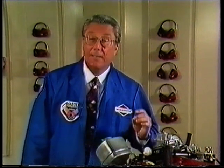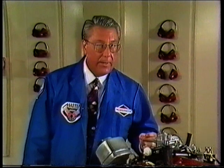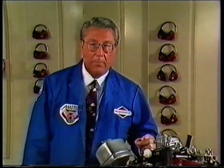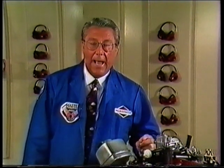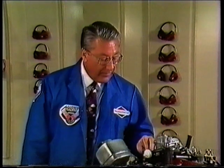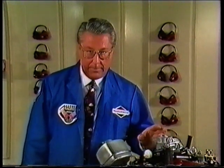In most of these hunting and surging problems, the cause is a lack of fuel, not an overly rich fuel condition. And believe it or not, more than 95% of all carburetor performance problems are caused by dirt or debris in the system. However, before you can accurately diagnose a performance problem, you have to determine whether you have a governor problem or a carburetor problem.